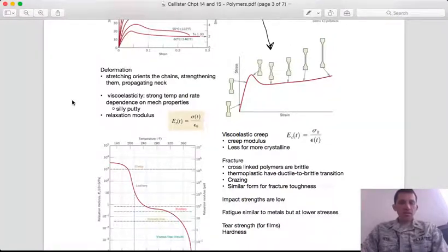And that is a completely different mechanism from the strengthening of metals. Remember, in metals we strengthen them by preventing them from deforming. In polymers, actually, it's the deformation. In metals, those dislocations that are formed during deformation impede the motion of other dislocations. In polymers, we see that it's actually a reorientation of the polymer chains relative to one another, not necessarily them impeding each other's motion.